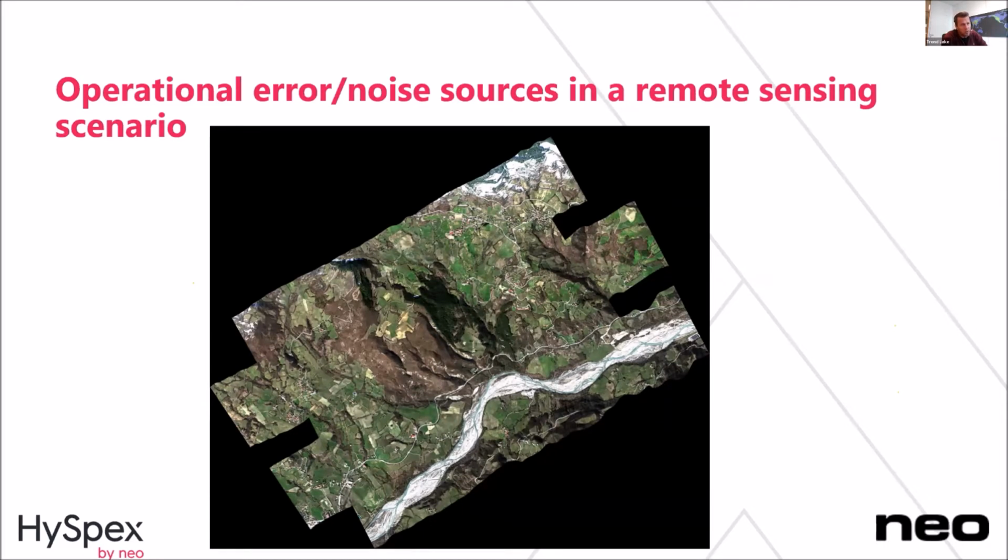That's a really important part of designing any airborne platform. If you have a bad platform or bad camera, you can try to correct for it, but it will be quite hard, because when you start a campaign and open the hatch, or it's always open, depending on your system, it will change a lot during the first couple of hours, and you would constantly need to do stuff if you have an unstable platform.